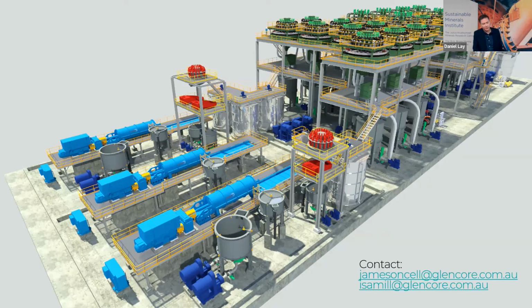Yeah, so I suppose the Jameson cell can be seen in two parts. You've got the Downcomer, which gives you that very high air to pulp ratio, very high number density of bubbles, and a very highly turbulent environment. So essentially, you're slamming this jet of slurry into a foamy bed where you're going to get significant contact between air and particles.